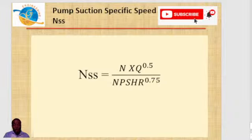So it's also very important to look at some of these parameters and check whether the suction specific speed obtained from a given pump manufacturer is in line with the conditions stated in API 610.